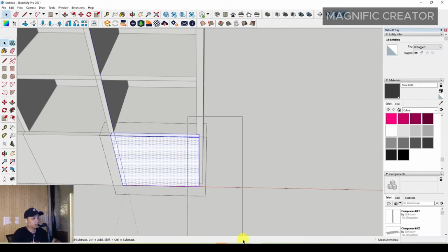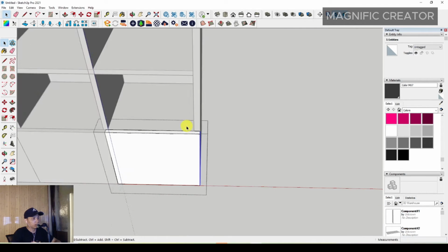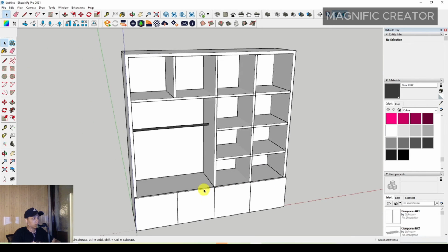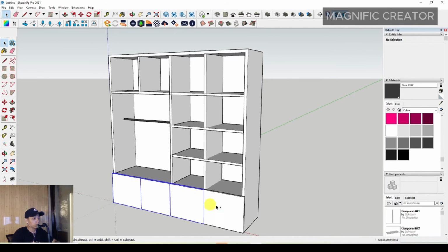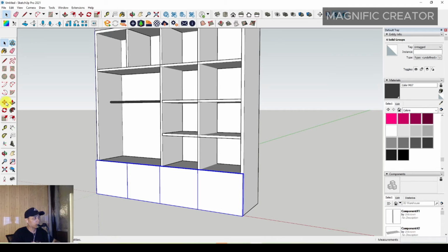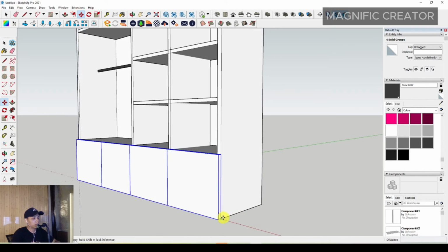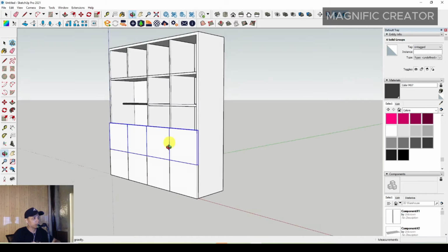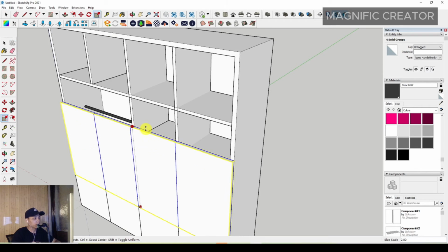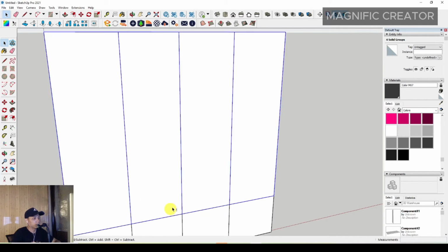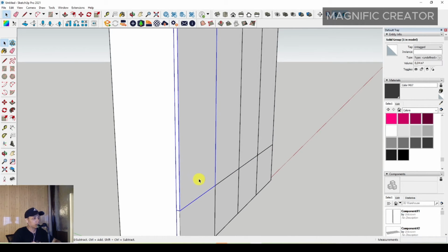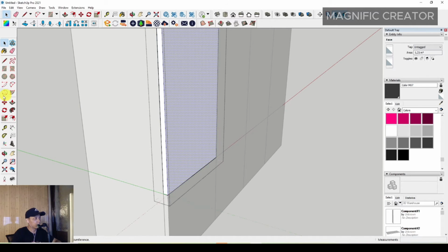then you have to adjust the length to extend this cover, this little door, and after that you can move all this wardrobe lower door to the upper position by selecting move and pressing control to duplicate it, and you can select the scale to scale it until it's on the upper position right here, and after that you can make more thickness of each upper door of the wardrobe right here.